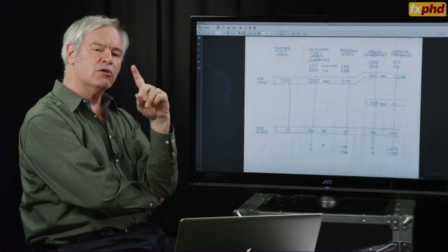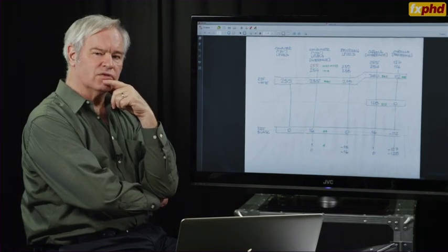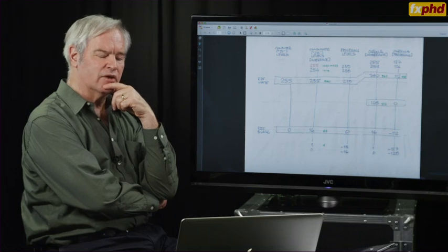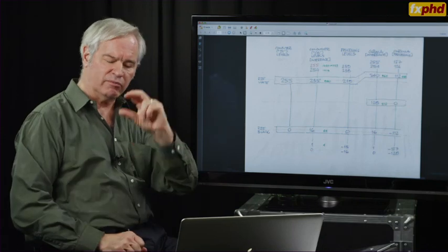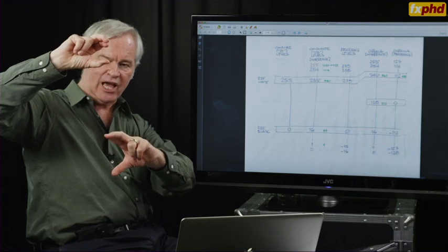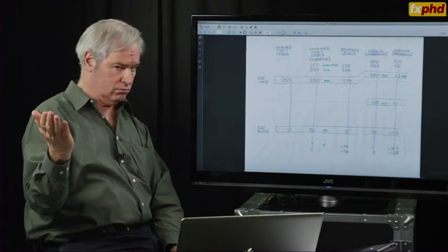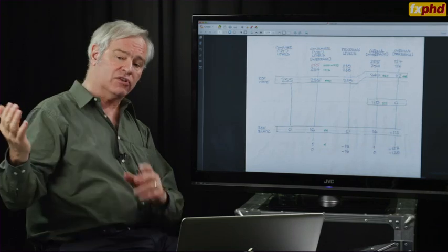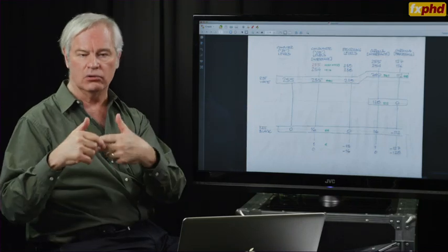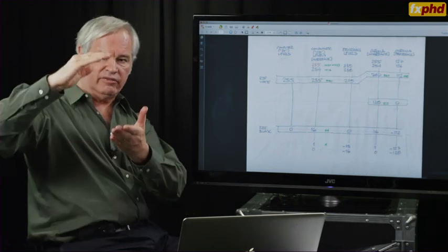But for studio video, the situation is a little different, because in the early days of studio video, 3 or 4 different reasons were identified that made sense to have some footroom region and some headroom region, footroom below reference black and headroom above reference white. Now, one of the reasons 25 years ago was that digital video was basically retrofitted onto huge analog video infrastructures, and analog video drifted around.